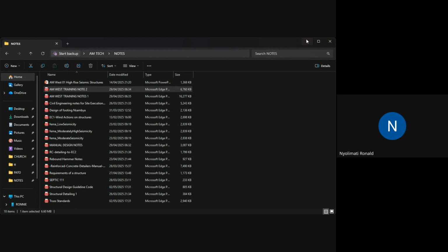Maybe you put another column here, then another column here. This spacing here, you may find it is 1 meter. This is also 1 meter. So at least the minimum spacing of a column will be 3.5. So I can come and erase this one.